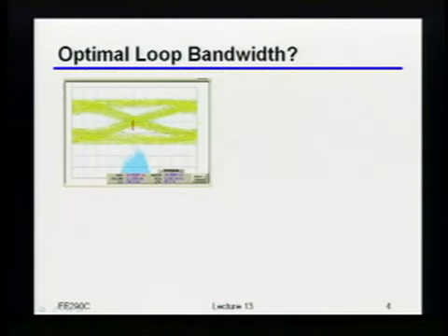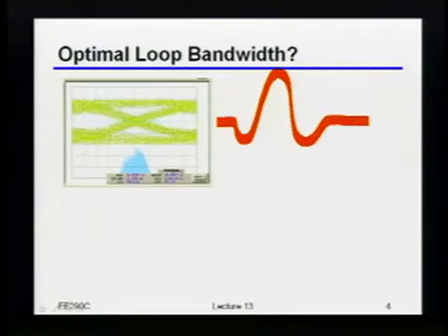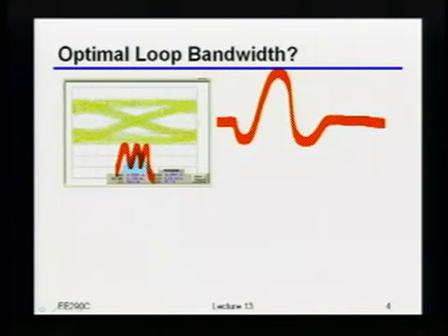In fact, a lot of times when you build the equalizer, it can turn out to be even worse than this, because as I mentioned before, when you build your equalizer at the transmitter, the transmitted pulse looks something like this, which you notice actually has multiple zero crossings in it. And if you've got multiple zero crossings, that tends to cause a multimodal distribution on the edge, okay? So the real point here is that on your edge, you're going to have quite a bit of ISI-induced jitter. Okay? So, what does that say about how you would like to build the CDR loop?